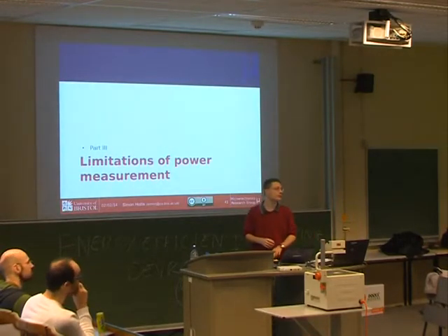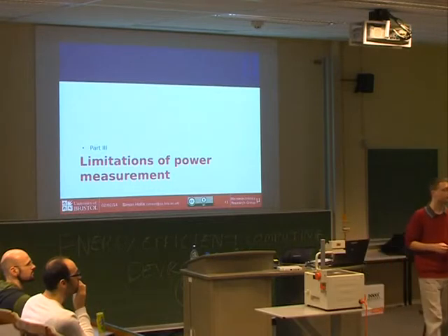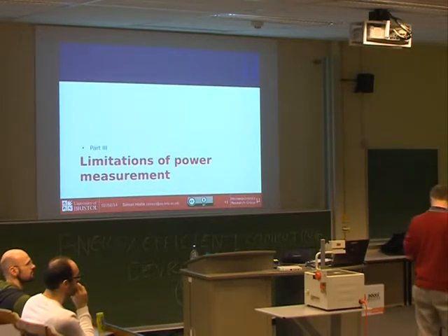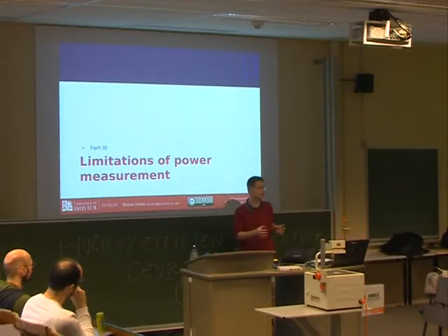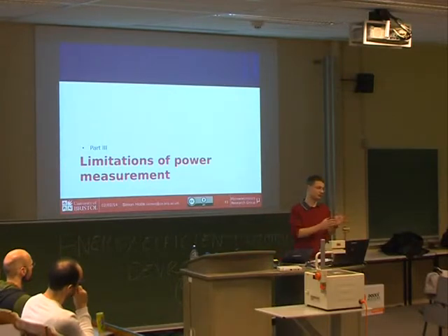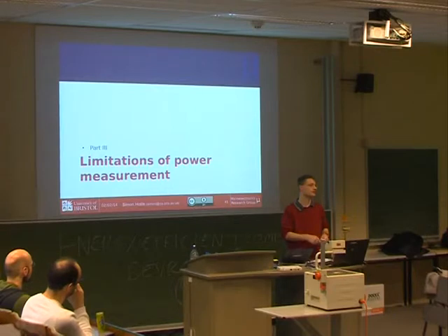Any more questions? Do we need to be concerned about the tolerances on the shunt resistor? Yes, absolutely. So the power consumption measurement you get is directly proportional to the resistance. So if the resistance changes, or has a tolerance error, then your measurement is affected by that as well. You can of course measure the resistance with a scope or a multimeter. For this reason, again, shameless plug, in the open source design, we specify some very tight tolerance resistors, 0.5% resistance, to minimize any differences.